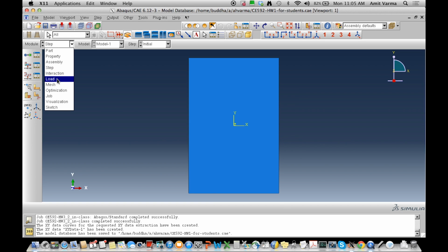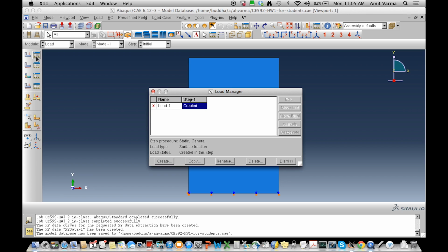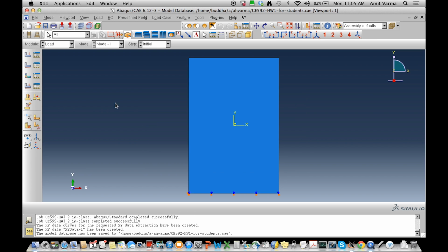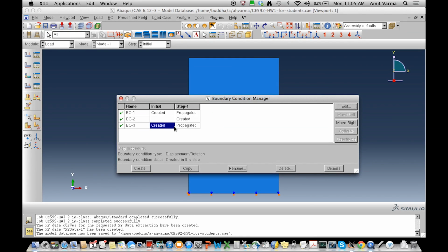Now what I want to do is subject this same plate to strains in the longitudinal direction and in the transverse direction. Both of them are equal to 0.01. I really want to subject it to a state of biaxial plasticity so that I can better understand what the Prandtl-Reuss simulations are going to show. Those are the ones that have been programmed into Abaqus for the elastic, perfectly plastic case. So in order to look at that, I want to subject this analysis to a biaxial plastic strain of 1%. How should I go about doing that?